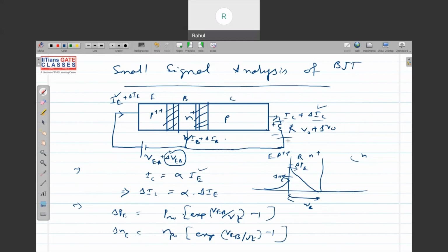So when you connect a resistor like this, for signal and output, you see, this is positive, this is negative. This may forward bias the base to collector junction. So there should be a bias VCC in the reverse direction. This is the bias voltage such that for all the signal and the quiescent operating point, VCC plus this voltage is negative, so that the base to collector junction is reverse biased. Okay, this is the use of this VCC.